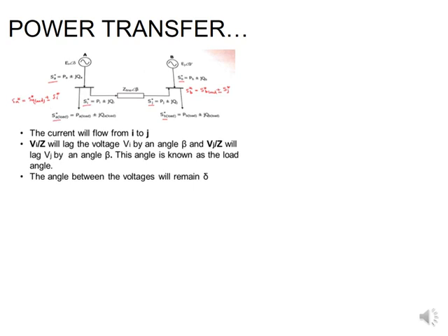And what you want to be generating for, you're wanting to generate at either A or B such that they can be able to feed their load, number one, but they must also be able to supply that interconnector, which is your line going from A to B, and the load at the other side, just in case you had to lose one of these power stations in your network.